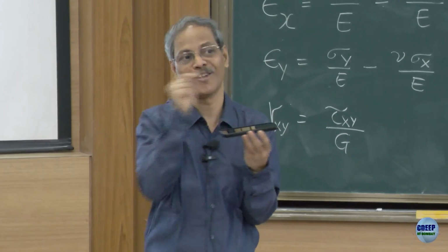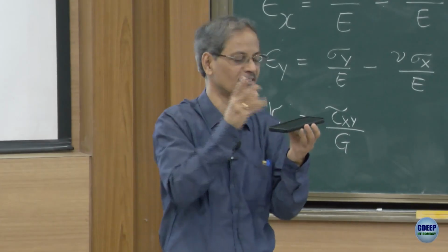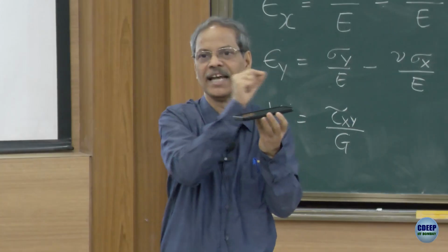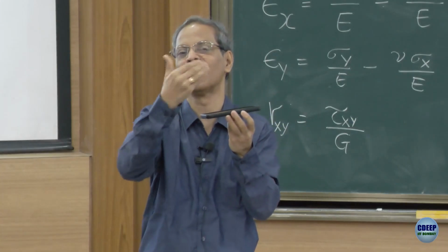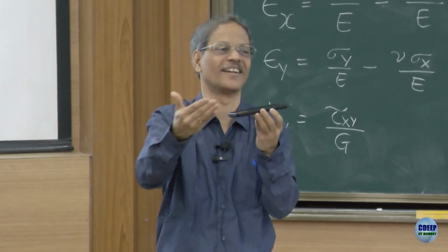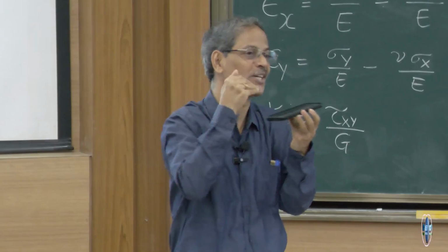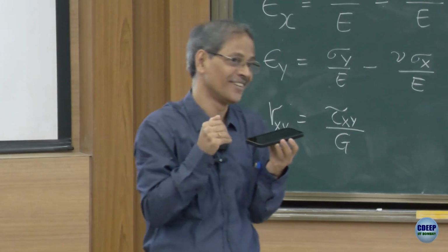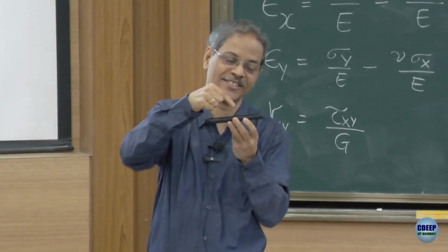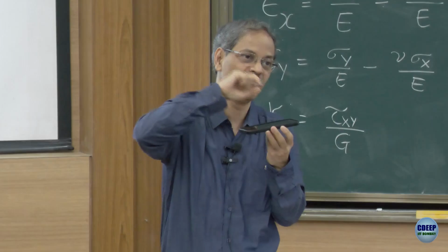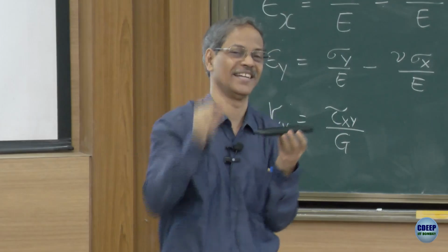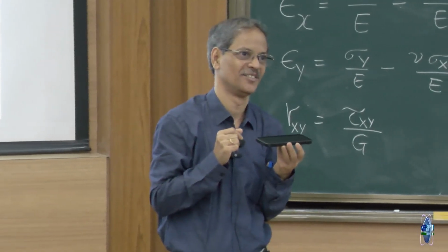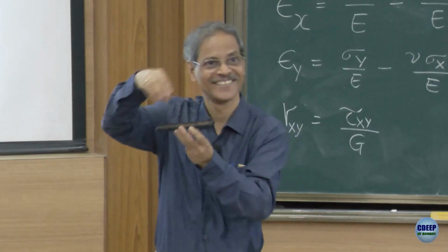So I have to model now, not simply as cutting it into pieces. A line element in 2 dimensions you would think of as a triangle or a quadrilateral, correct? But that's not how simple life will be now. It is possible that the geometry actually has a circular hole. However much you may try, you may not get an exact circle in your computer model.